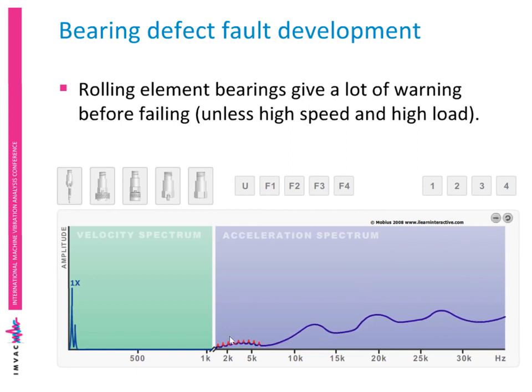But then as we go further, the acceleration, which is more sensitive to higher frequencies, will begin to change. And we can see it in the time waveform and spectrum, and as we go further, our traditional peaks in the spectrum that I'll explain a little bit more about in just a moment will start to develop as well. So the beauty of all of this is that it enables us to get an estimate or an assessment or an approximation of how long the bearing has to live.